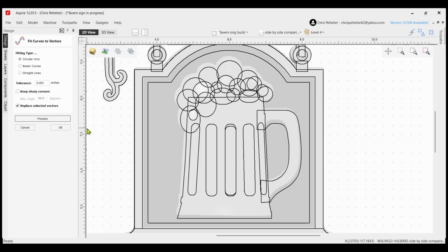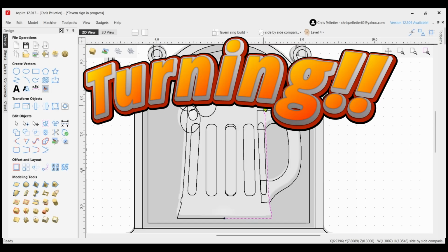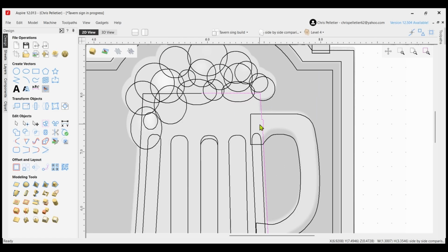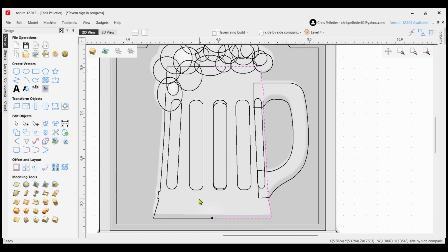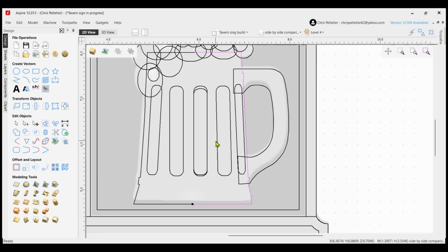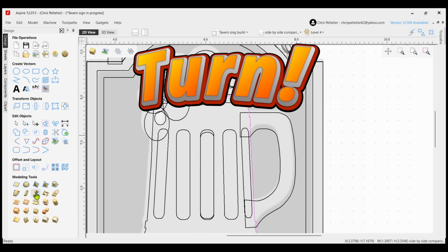And then what I also do is I will build this mug using spinning and two rail sweeps. So I drew my vector, and I knew I wanted a little ribbon here, and something here. So I drew these little vectors around it. And then when I did a spin, I used this spinning tool, which is creating a shape with spinning.